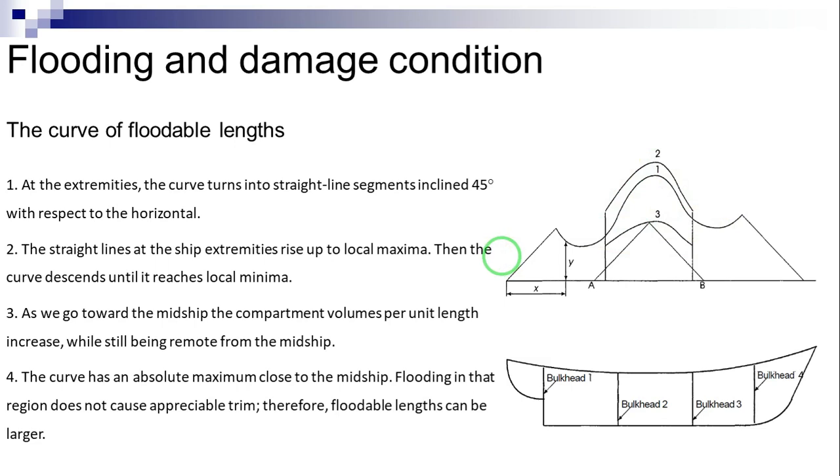The inclining experiment. It is usual to carry out the inclining experiment a short time before the completion of the ship. The vessel must float in calm water, and the work must be done while no wind is blowing. The number of persons aboard should be limited to that strictly necessary for the experiment. Their masses and positions should be exactly recorded. Tank fillings and free surfaces in tanks should be well known. Free surfaces should not reach tank bottoms or ceilings for the expected heel and trim angles.